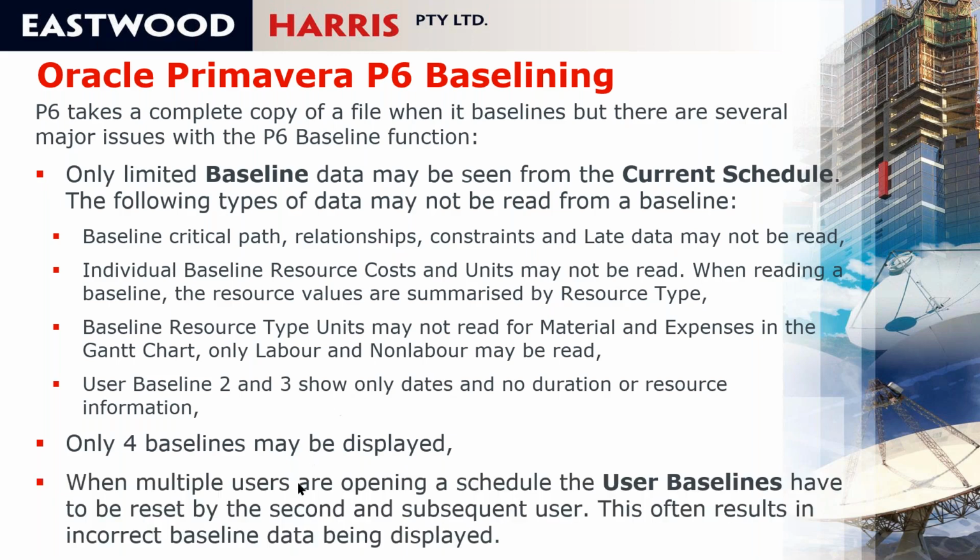And when multiple users open up the schedule, the user baselines have to be reset by the second and subsequent user. So if I set a primary baseline and a user baseline 1, and if somebody else opens up my schedule, they must reset user baseline 1 to the same as mine, otherwise they're going to read different data, which is quite an issue when you have multiple users in a project.